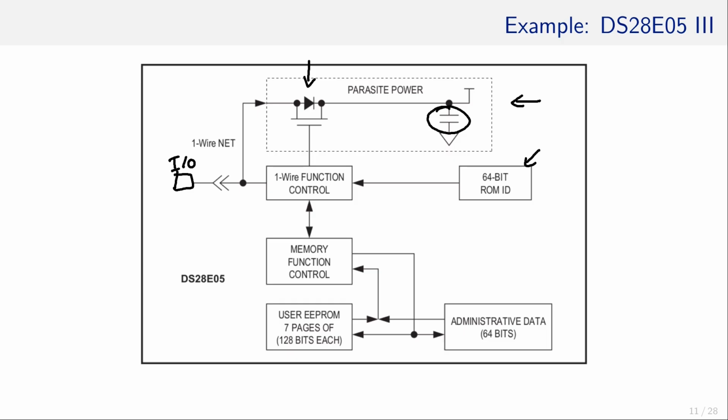If the I/O line is unused and is idling high at, for instance, 5 volt, the capacitor is charged. If the I/O line fails to supply power because someone pulled the line down to the ground to write a logic 0 to it, the capacity in this capacitor is enough to bridge over that time period, and it keeps powering the device till the I/O line comes up again, like a small independent power supply in form of a battery.